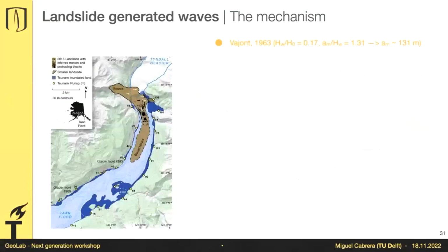So what we came out with was a way to allow a first order prediction of the wave amplitude if you happen to know the geometry of your problem. You might do a slope stability analysis and know the whole height of your slide. You know the water level conditions. And the density of water doesn't change that much. The density of the soil doesn't change that much. You have enough ingredients to predict the wave that a landslide generates.